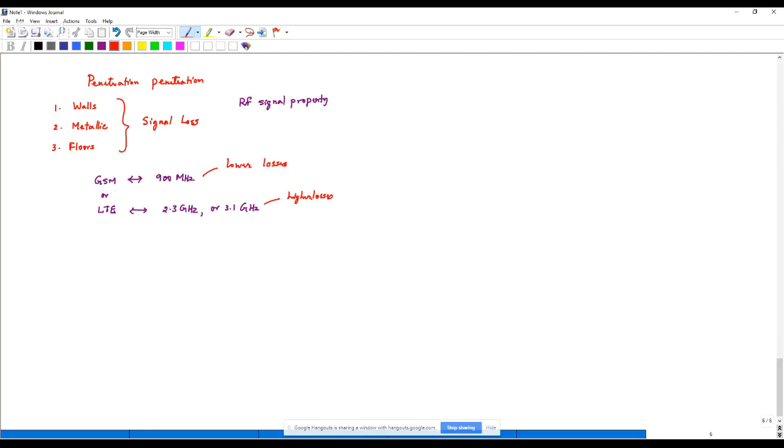Okay, and another important element: in this particular case, I am transmitting a 200 kilohertz signal. In this case, I am transmitting a 20 megahertz signal. So if you think about it in terms of the power that you are transmitting divided by bandwidth, then you can realize that LTE, because you're using, let's say, 2 watts of power, in one case it is being spread over 200 kilohertz, in another case it's being spread over 20 megahertz. Which means that inherently you're going to face signal quality issues based on distance with an LTE system.